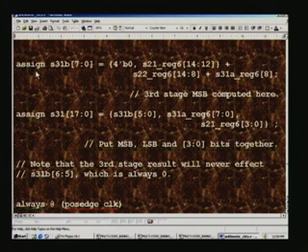Once again we use assign statements, and as usual we have put 4 zeros here, although you need not do it, and we take the MSB of the first number and the MSB of the second number, and as well this is taking care of the 4 bit shift, and you can cross check, you can see from here 14 through 12 is 3 bits here, and plus 4, 7 bits here.